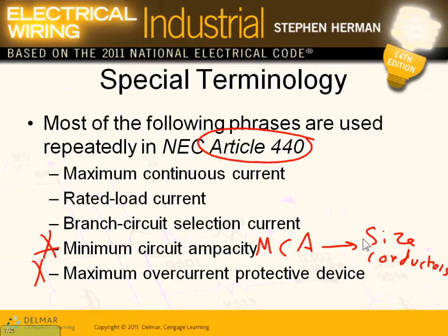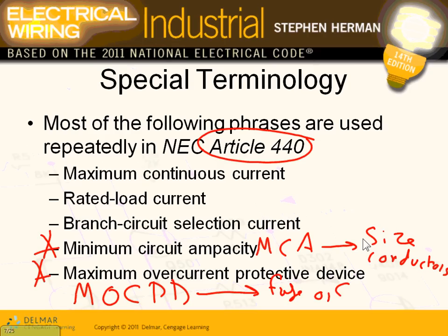The second very important thing is maximum overcurrent protection device. This one you size the fuse or circuit breaker, no question asked. These are printed on the nameplate of this mechanical HVAC equipment. This is mainly for chillers and compressors, not fans. These are typically for anything that has a hermetic motor, a compressor, some type of a compressing system coupled with the motor. That's how they do them. Article 440, HVAC. This is the cooling part.